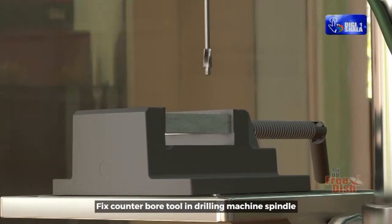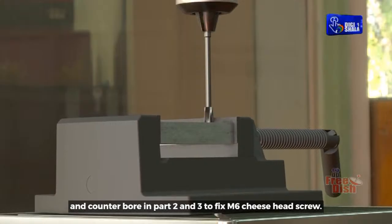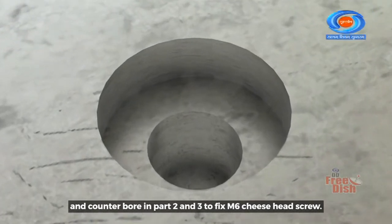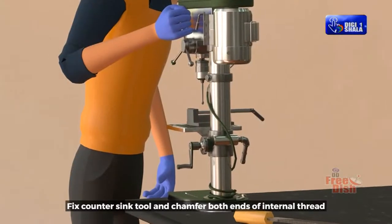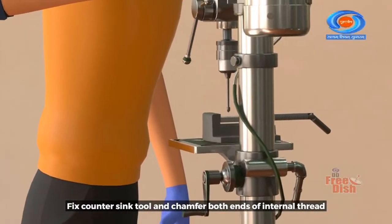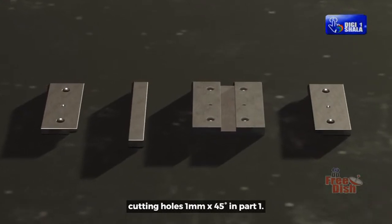Fix counter bore tool in drilling machine spindle and counter bore in part 2 and 3 to fix M6 cheese head screw. Fix countersink tool and chamfer both ends of internal thread cutting holes 1 mm at 45 degrees in part 1.